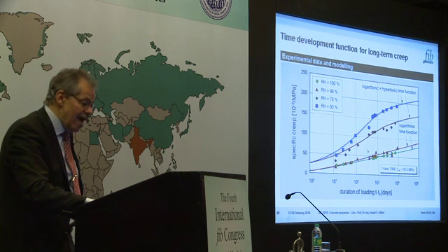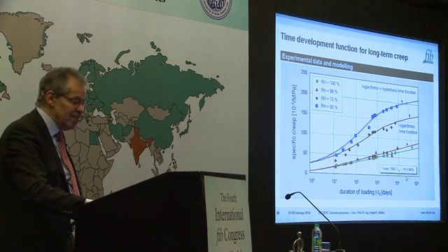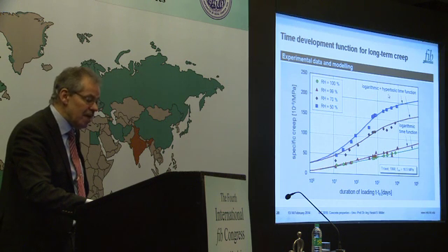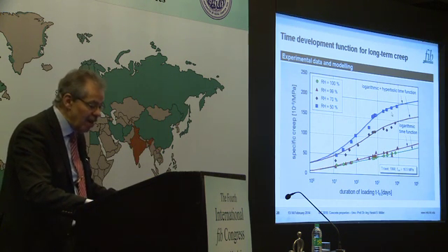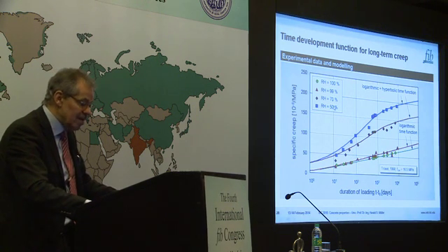First, see the time development. You have here for basic creep only the log function, which is a very straight line, with very long durations of loading in these tests, over 13 years. And if you add up the logarithmic and the hyperbolic, this is basic and drying creep, you cover these curves very well for a dry ambient environment.